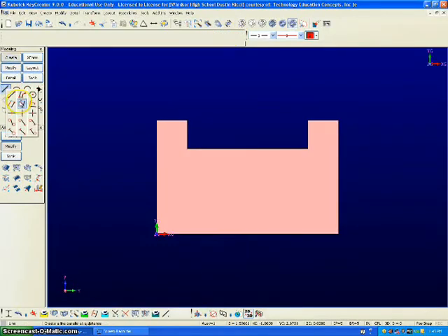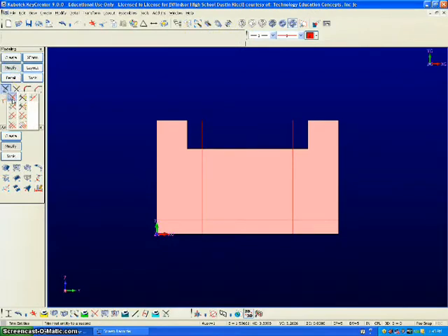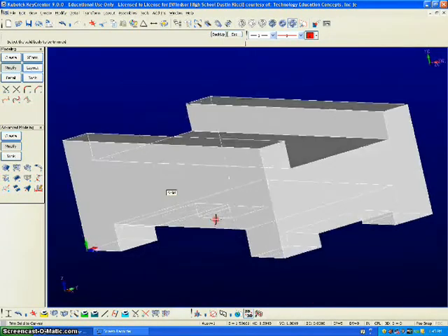Now we're going to do the same thing, except this time on the bottom. Create line parallel distance. And this time we're going to go 0.75 from the sides and 0.25 from the bottom. Modify trim entities, trim first, just like that. Now we have our 3 trimming curves, so we're going to go to modify advanced trim solid curves, OK. Select the 3 trimming curves, accept, and select the main body, and again to your left. Now that is trimmed out of both sides.